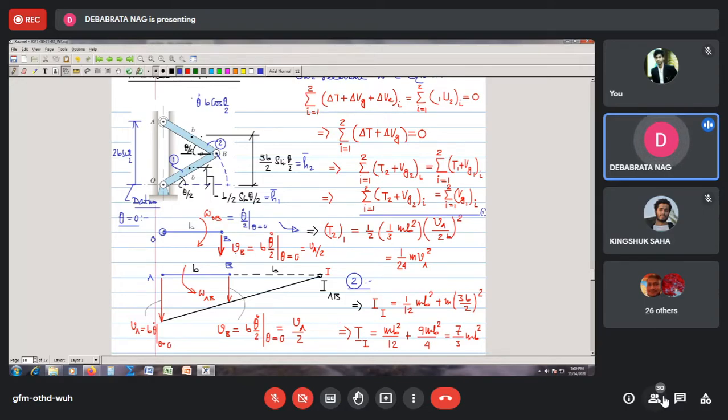One advantage is that you do not have to calculate any acceleration, so everything is limited to finding the velocity. And since the instantaneous center is specific to velocity, the solution by the instantaneous center method is very attractive, the way I have solved it in this problem.